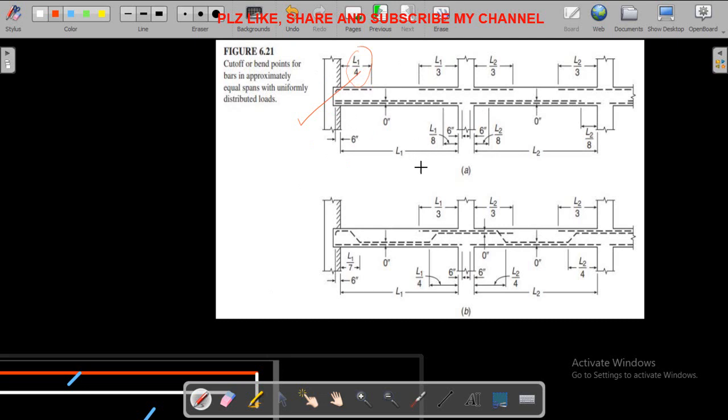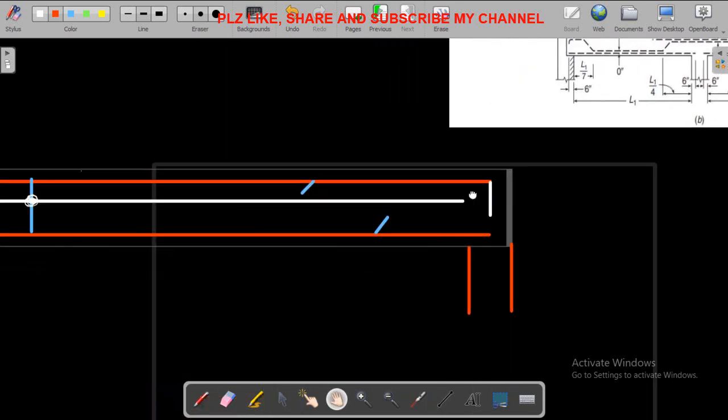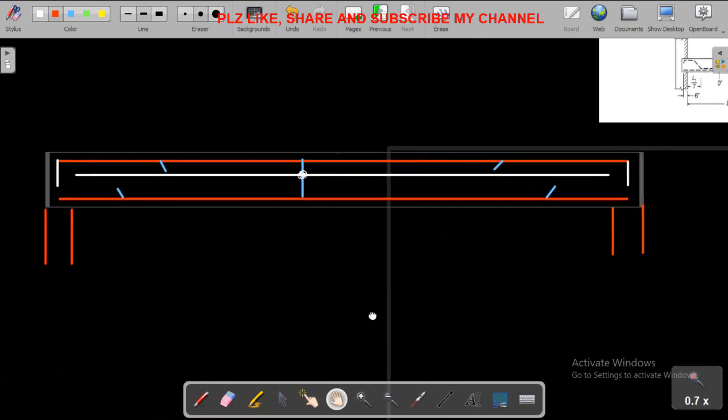But in the case of simply supported beam, it is cut off at a distance of Ln/20, right? So in the case of simply supported, because it is a continuous beam, in a continuous beam the detailing is different, while in the simply supported beam the detailing is different, right?